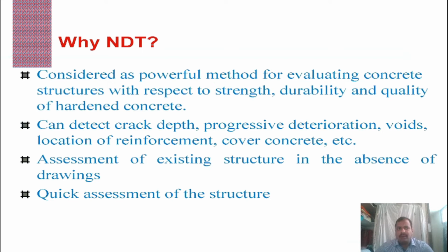Now, where can we apply this technique? The typical situations where NDT can be useful are: quality control of precast units or construction in situ; location and determination of extent of cracks, honeycombing, and similar types of flaws and defects within a concrete structure; determining concrete uniformity, possibly as a preliminary to core cutting, load testing, or other more expensive or destructive tests, deciding which type of test we have to carry out; determination of position, quality or condition of reinforcement; increasing the confidence level of a smaller number of destructive tests; determination of extent of concrete variability to help in selection of sample locations.